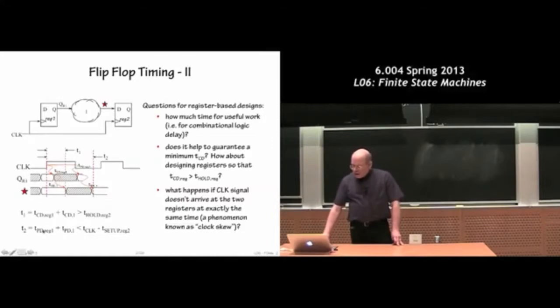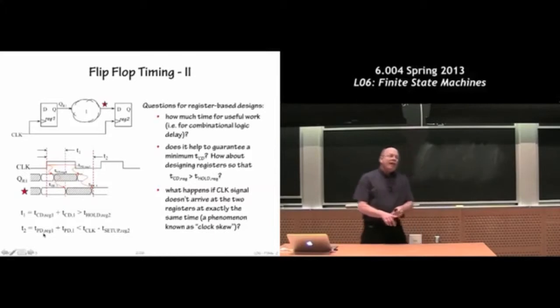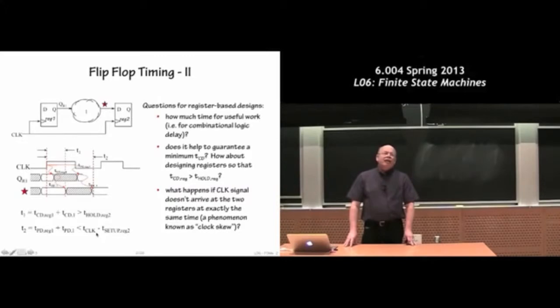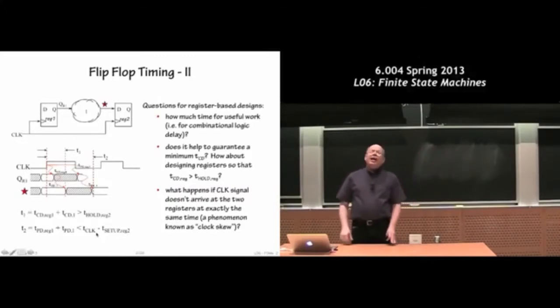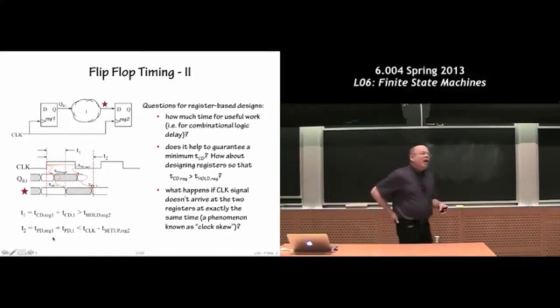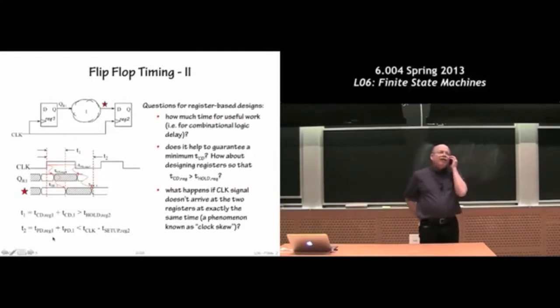What they've done is that they've been carefully testing the circuits to see what their actual propagation delays are. And then they pick a clock period that makes the second timing constraint true. In other words, simply by changing the period of this external clock, I can make the second timing constraint true. Right? Because the hardware will have whatever delays it has, so the setup time and the propagation times, that's what the hardware will have. But whatever it is, you can make the clock period big enough that everything that has to happen between rising clock edges does. But what about the first timing constraint, the contamination delays?